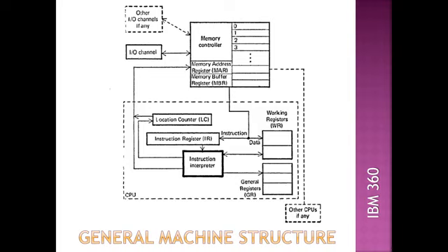Similarly, I'm going to say what is going to be stored where. First, the 2000 address will be stored in the memory address register, right? And the value at that address is nothing but your load instruction, and that is going to be stored in your memory buffer register. So addresses will be stored in the memory address register, and the value at that particular address, which could be an instruction or could also be data, is going to be stored in the memory buffer register. Let us see another example.